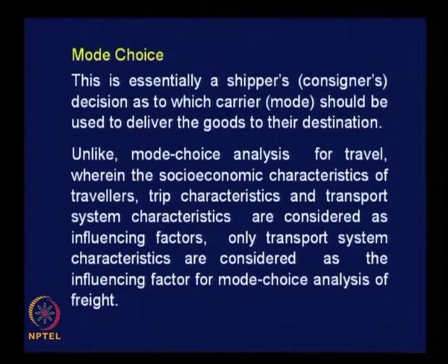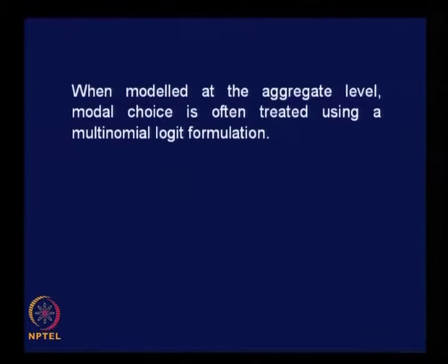Okay. Characteristics related to transport system. And when modeling at the aggregate level, the modal choice is often treated using a multinomial logit model, as we did in the case of passenger transportation. The analytical tool is the same as we used earlier.